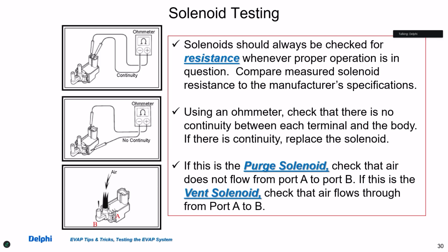As far as the components themselves, whether it's a purge or a vent, they all have coils in them. They all have resistance values. Typically about 68 degrees Fahrenheit is what the spec comes with. And if they don't give you a spec as far as plus or minus, so let's say it's 45 ohms, I like to use the rule for temperature change of 35 to 55 as a range. And that's stretching a little bit, but that's an indication right there. But I want you to remember on the solenoids, just because they pass the ohm test doesn't mean when it gets hot it's going to work.